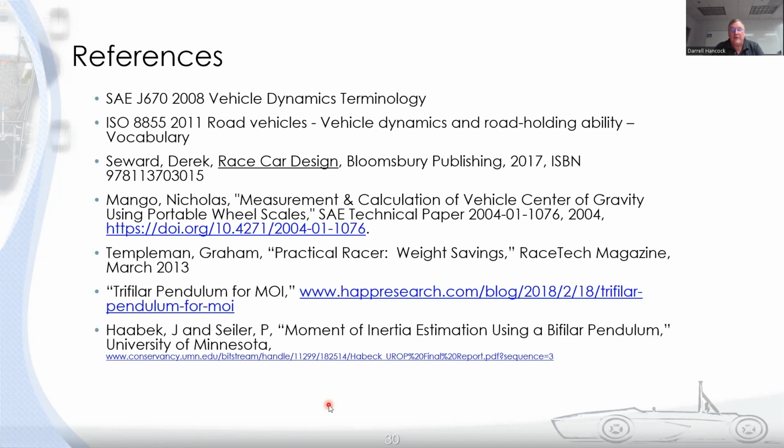And you will probably see bigger variation if you do measure the inertia of your vehicle, because you're not going to have the inertia of the individual parts, right? For some of the larger parts, it's important to have that, say your engine and transmission assembly. You need to figure out the inertia of that part, which is not going to be a trivial thing, right?